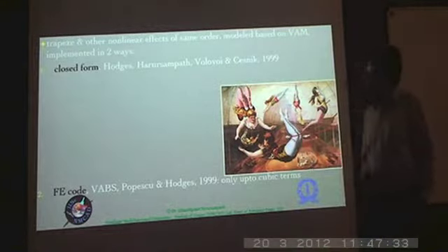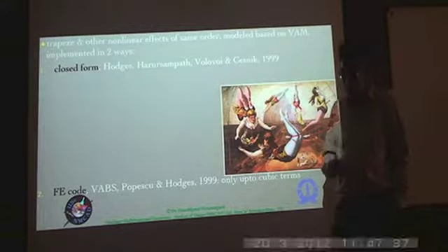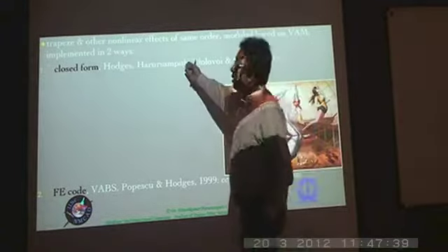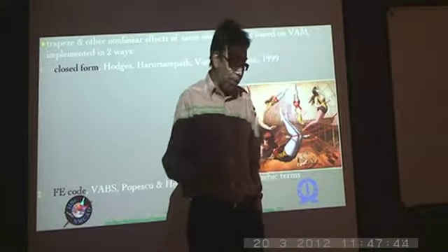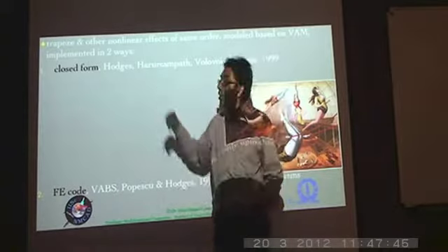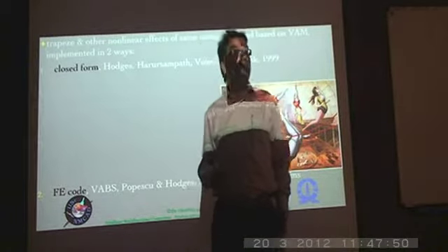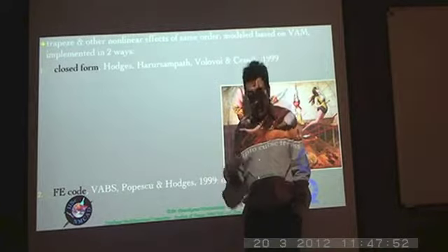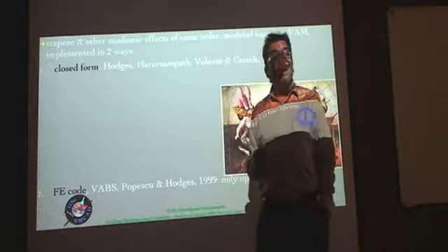The other situation is where you have much more complex geometries, because this is restricted to thin rectangular strips, and later the closed form analytical solutions have been extended to thin-walled open section beams as well, which are made out of strips, like for example I sections, channel sections, etc., which are also very practically relevant.